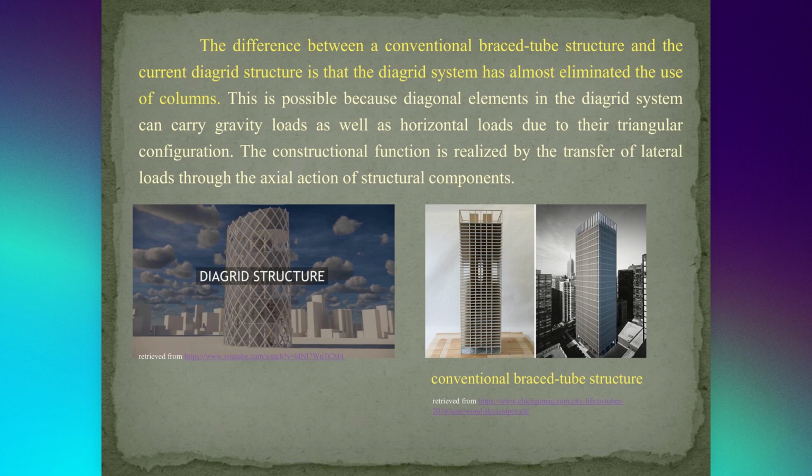This is possible because diagonal elements in the diagrid system can carry gravity loads as well as horizontal loads due to their triangular configuration. The constructional function is realized by the transfer of lateral loads through the axial action of structural components.